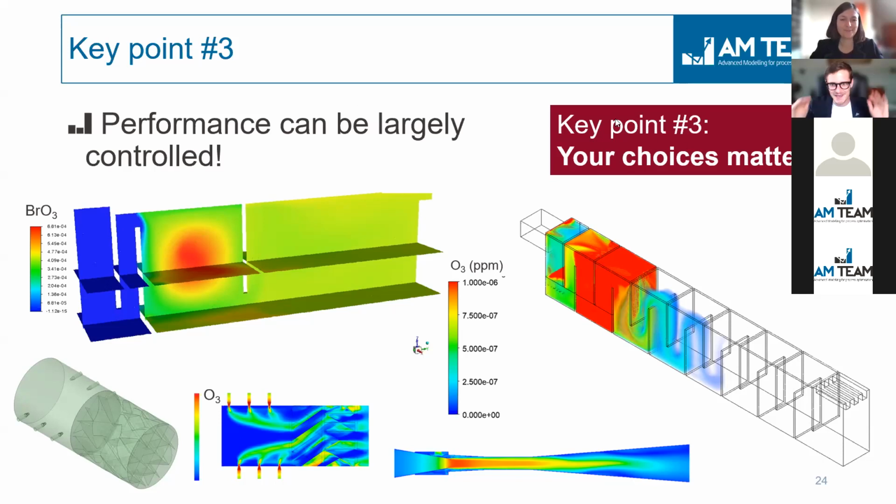Because this brings us to the CFD slides. And yes, full-scale reactors have non-ideal dynamics. So mixing is very complex. You always have some short-circuiting, some dead zones. For example, in this reactor, you can see some rotating zone. I agree, it's a poorly designed reactor, this one, but we are showing quite an extreme case.